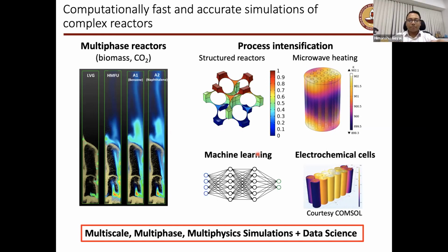So first of all, the biomass conversion techniques we are looking at is thermochemical conversion here. So it's basically taking known food sources of biomass and applying heat. So maintain temperature about 500 to 600 degrees Celsius if we are interested in liquid fuel, or about 800 to 1000 degrees Celsius if you're interested in syngas, for example.